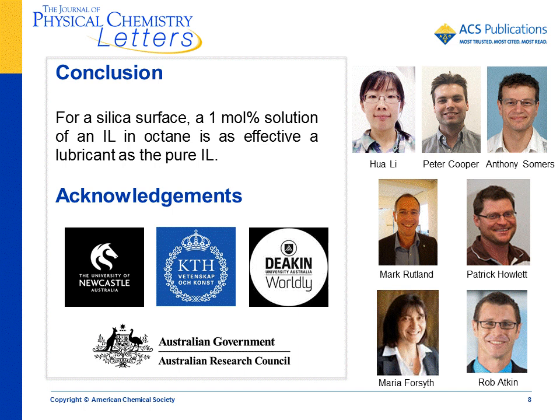To conclude, for a silica surface, a 1 mol% solution of an IL in octane is as effective a lubricant as the pure IL. This demonstrates that by using ILs as oil additives, we can achieve a similar performance to the pure IL at a fraction of the cost.